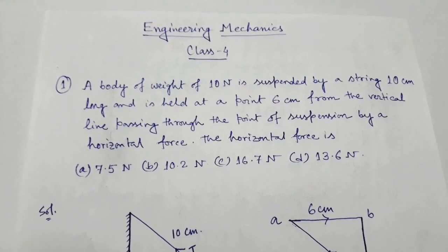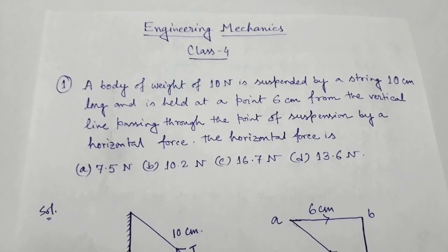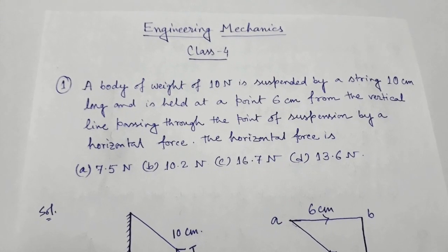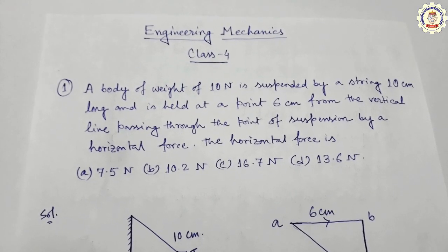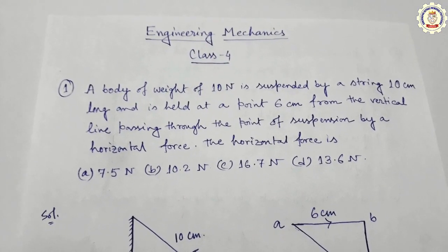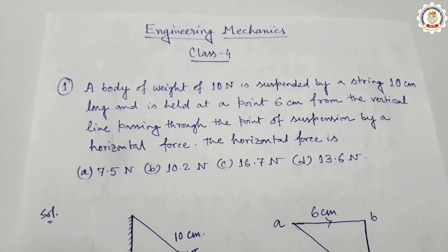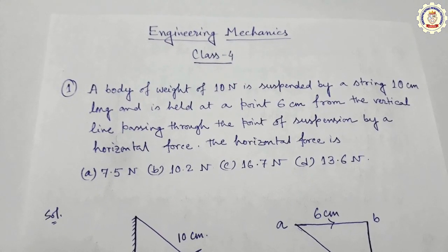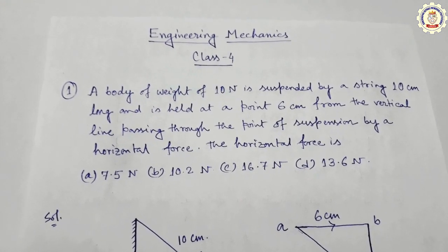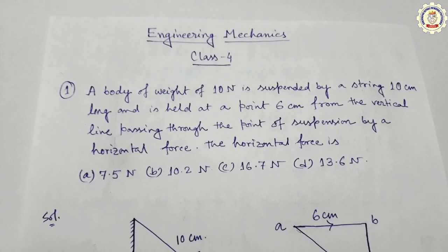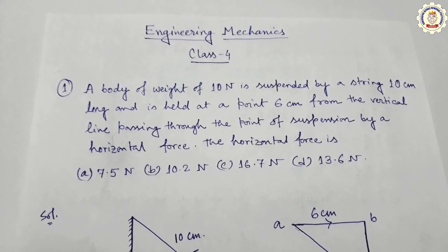In my first three problems, the systems discussed are in equilibrium, and as such the lines of action of all the external forces must be concurrent, that is, meet. The solution is then obtained by drawing the free body diagram for the system and the corresponding force polygon. So let's focus on the first problem.